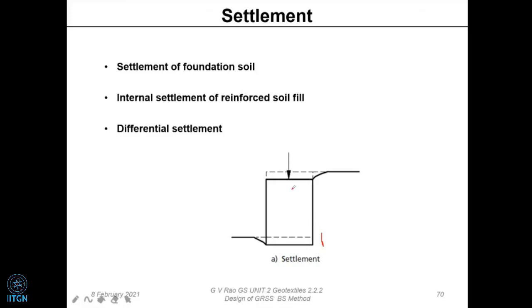Also, our fill material, as you keep compacting from top to bottom, will compress instantaneously. If it has high clay, it is going to settle more. So we are going to talk of the settlement of the reinforced fill zone and also the foundation. These are the two things.